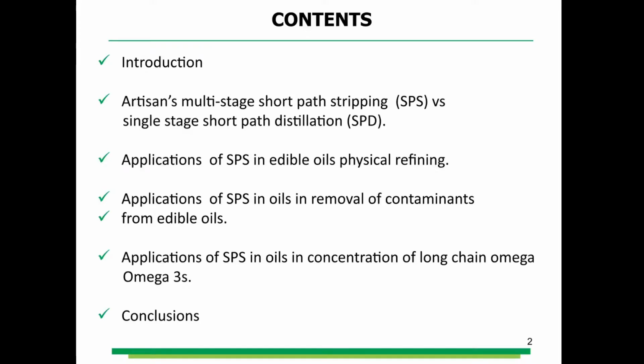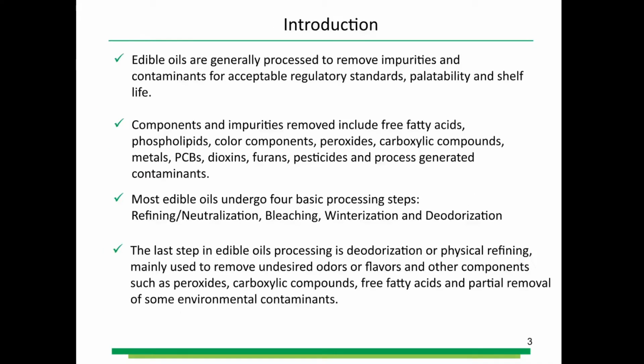Then we will talk in more detail on Artisan's multistage short path stripping technology compared to the single stage short path distillation processing. Then we'll go into applications of this new Artisan technology in edible oil physical refining, removal of contaminants, and also on the concentration of omega-3 fatty acids.